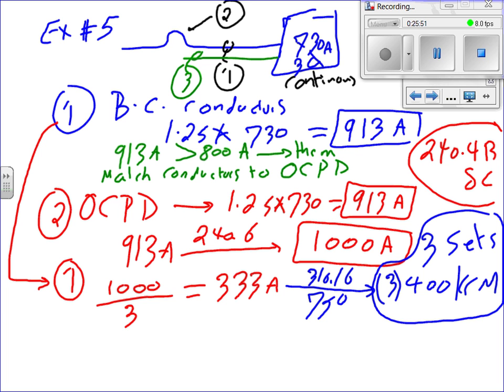So under the 75 column, you need to find an amp of 333 amps or more. You can't go to 330, for example, because your amps are 333. So it's 350. And then in that column I have 310. No, you have 335. There's a 335 there in the column. Oh, I see. Okay. You mean that you went to 400? Yes, I see. Okay. Not 350.